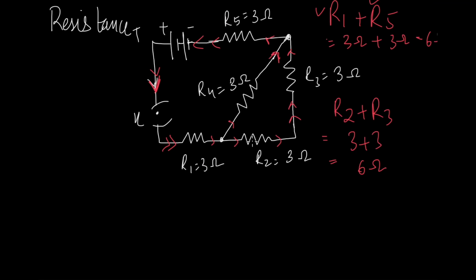In front of both R2 and R3, R4 is placed, so it is in parallel with both of them, because when the current is entering from R1 into R2, the current is bifurcating into R4, and when the current is exiting from R3, current from R4 is also entering that stream. So I can say confidently that R4 is actually in parallel with both of these resistors.